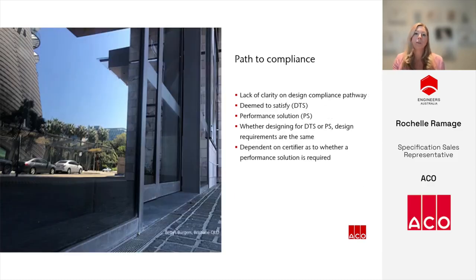One of the biggest issues we still see is a lack of general clarity around the compliance pathway. Designers often ask whether a level threshold detail is considered deemed to satisfy or whether it triggers what is known as a performance solution. To differentiate the two, deemed to satisfy is a prescriptive approach. It lists exact materials, dimensions, and construction methods. The performance solution is a tailored solution that achieves the same result with the project objectives in mind.